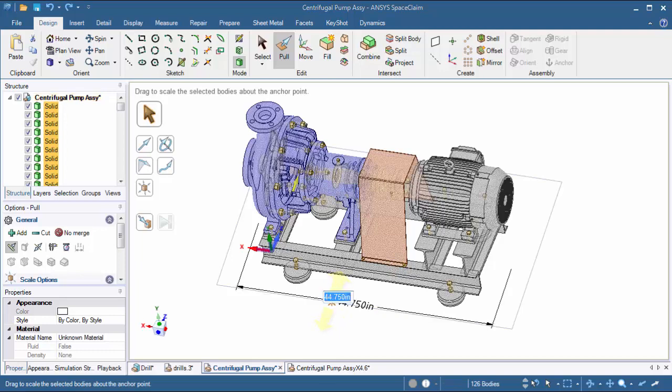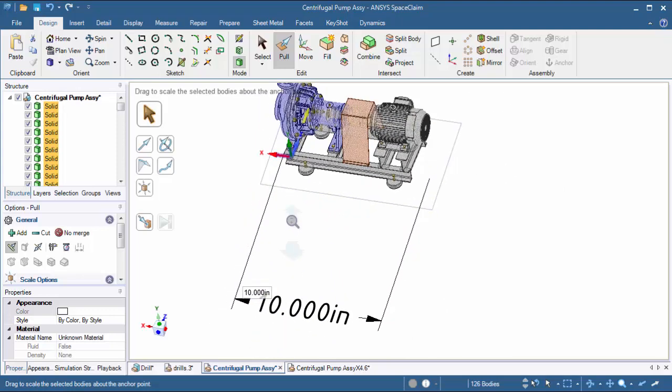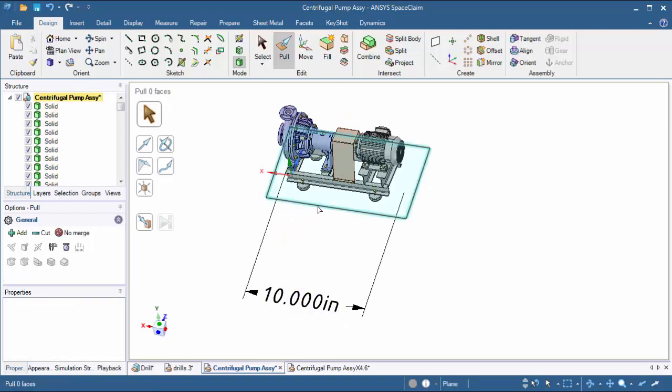And if I click that, let's say our print bed is 10 inches. So I'm going to do an even 10. We may want to round it down to 9.5, something to give us a little space, but let's just use a nice rounded value of 10. What happens when I hit enter is I'm telling SpaceClaim to scale the model based on the scale point of the world origin until this dimension is 10, and it'll get it as close as it can through an iterative scaling process. Sometimes it might be like 9.9999, round, as close as it can. In this case, it was able to scale it right to 10. So what's really nice is I don't have to calculate any scale factors. I could just drive it with this dimension.